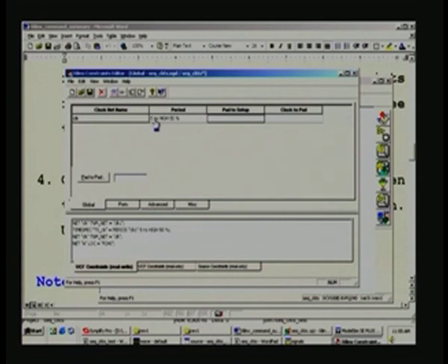You do not have to worry about any other thing. Nanosecond high 50%, it is a 50% duty cycle, it goes from 0 to high, and that is what the clock is for. The clock is listed here, and all other signals will also be listed, provided you get them from that UCF file, which is not done here. And now I will show another UCF file with all those pins we have mapped earlier.